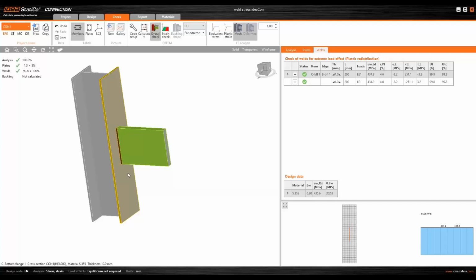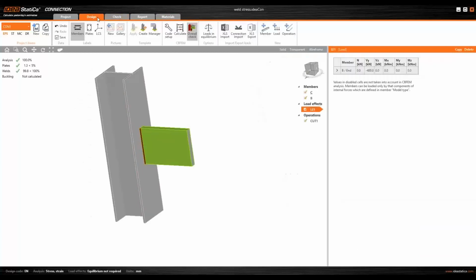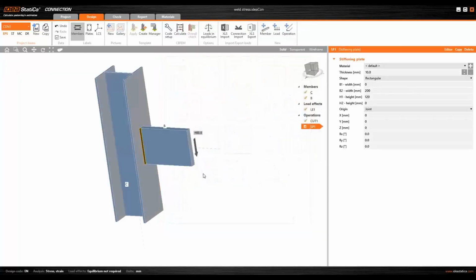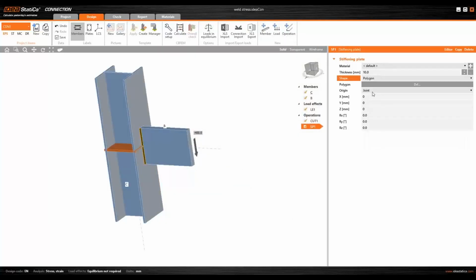Yes. Usually you have some objects in AutoCAD, so please try to disconnect to really simple. Yes, explode. If you want to import in DXF, it has to be in the most simple form. So if you have it in AutoCAD, for example, as an object, you have to explode it out to just simple lines, and then you're able to import it.